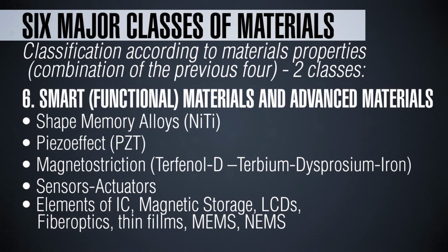And this is used in commercial alloys, which are called Terfenol. So Terfenol-D is the synthetic substance with the highest magnetostriction coefficient, meaning that it is possible with a small applied magnetic field to produce huge variations in its shape. And it is applied in linear engines. Another application for the magnetostrictive materials is that of the sensors.